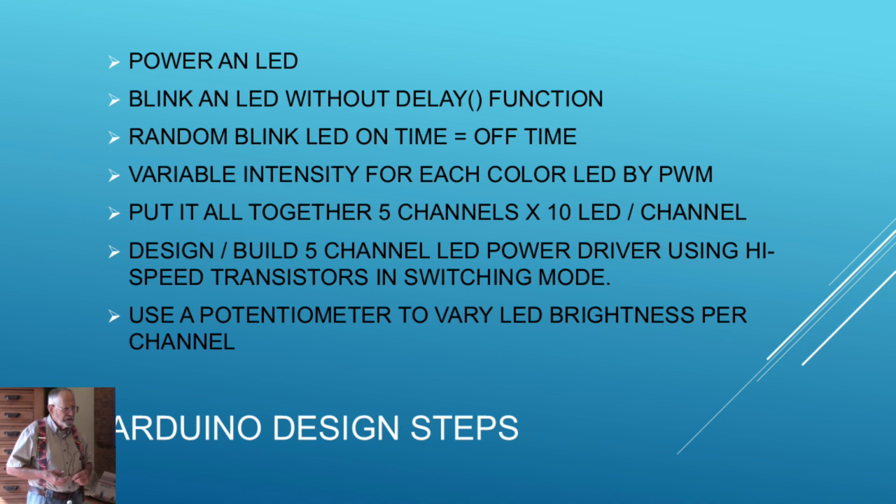And pulse width modulation in an Arduino with 5-volt outputs, that LED gets 5 volts when it turns on through that high-speed switching transistor, 100 milliamps per channel. And at some time later, it shuts itself off. If it's on full, you see full brightness. You see 10 milliamp brightness per LED. But if it's only on half the time, your eye and your brain think it's dimmer, right?